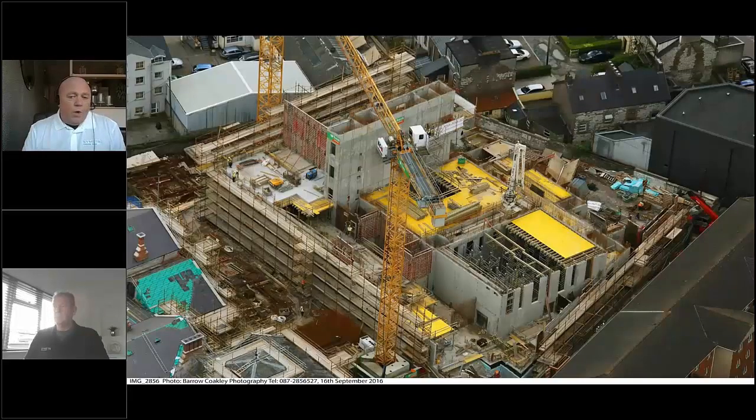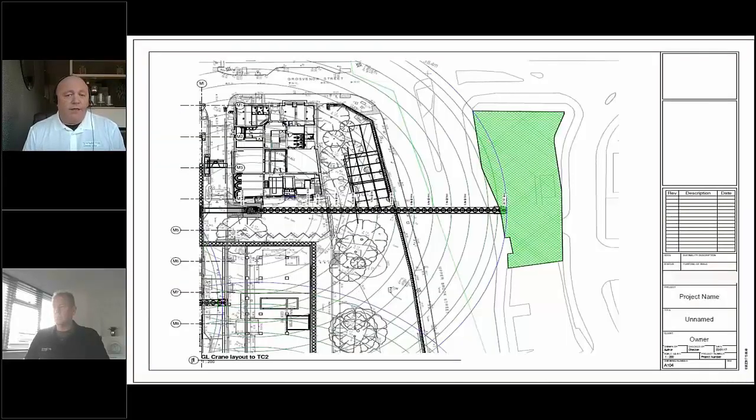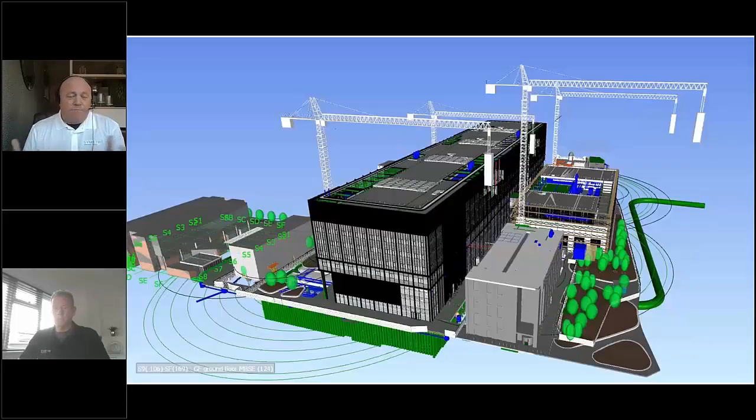And we know that things like the temporary works on site, placing that tower crane, because when we place it, we're using it for other things. We're looking at that lifting circle to make sure that we can lift the correct weights across the site, and it doesn't encroach other owned areas, landscaping and buildings and things like that. But if we can place them quickly into models, that'd be great to get drawings out like this, because temporary works are huge really when you start looking at how much goes into there with the hoardings, the site location and things like that.